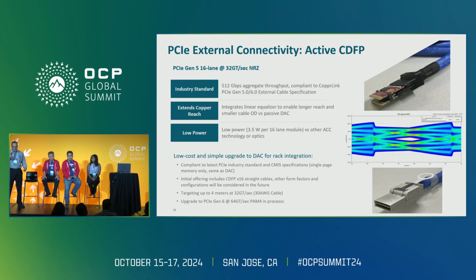Now that can easily be scalable down to a by 8 and even a by 4. And it's fully compliant to the PCIe specification, the TA1032, so it's interchangeable, and that's I think a big deal, where if you have a redriven cable, you need long links where you use longer cables, and for shorter links you can use the passive cable, so you can mix and match, so it's the same form factor. And so we're integrating in this particular cable 2 by 8 linear redrivers.